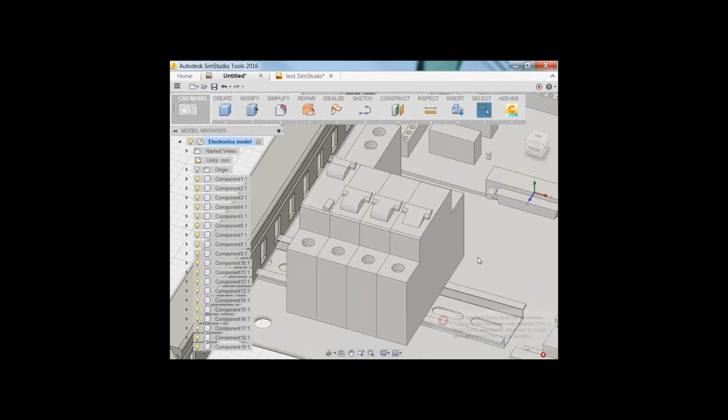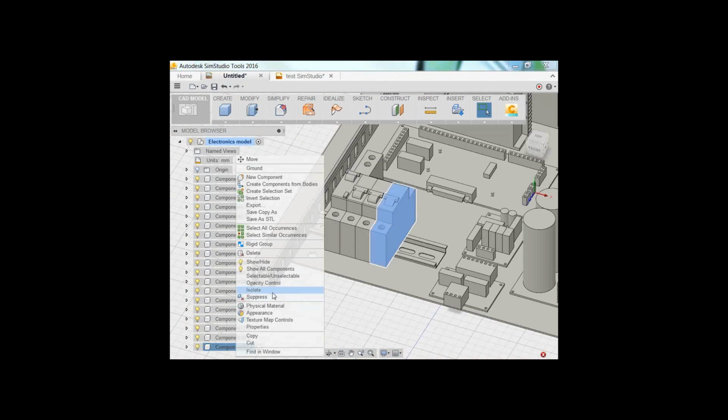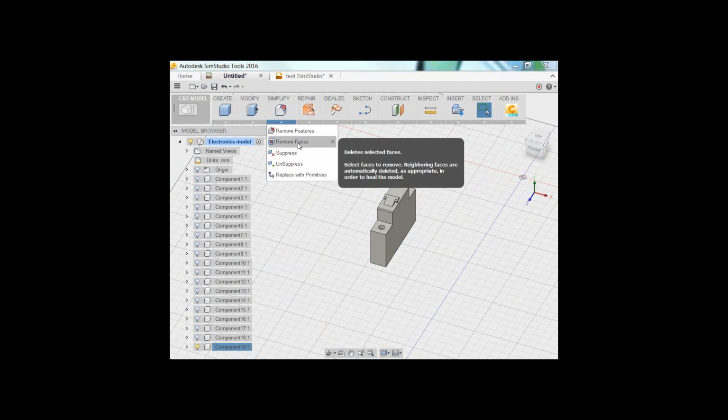Again, I'll go ahead and isolate this component. You just click on it, look in the browser window, and we can isolate this. Now, the reason I'm isolating it is I personally like to isolate it so that I know if I'm clicking something, I'm not accidentally clicking a different component. Especially when we're deleting things, you don't want to accidentally delete a different component. Again, this is just a workflow that I personally like to use, so I don't feel. Good tip, James. Yeah, don't feel compelled to have to, but definitely, and I'll give you a better example in a little bit.